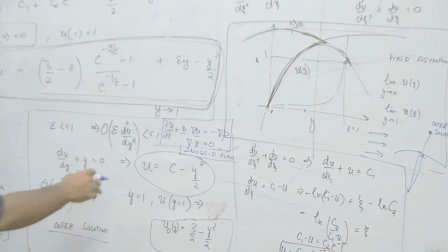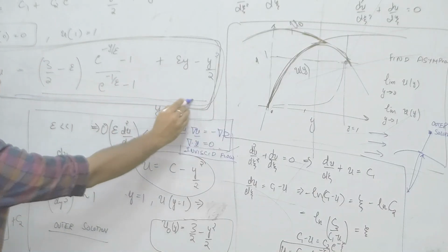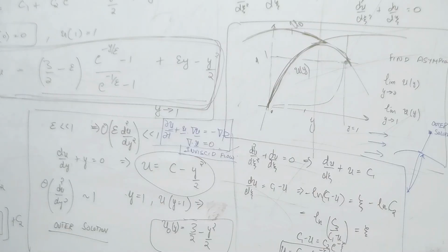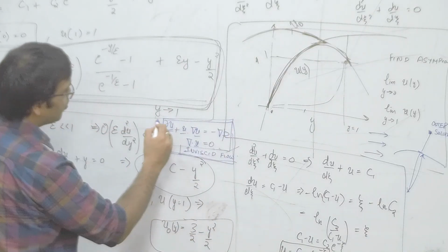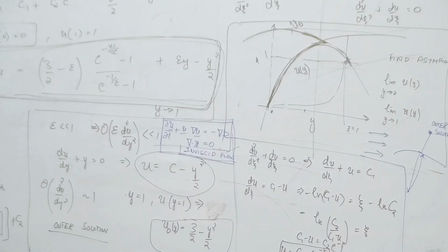And now, we don't know the analytical solution of this equation just like we did in this case, but we have some physical boundary conditions and physical reasoning which can help us out in determining which boundary conditions will take a hit when we specify inviscid flow. Some boundary conditions have to take a hit because we don't have second order equations anymore, we have first order equations. Which boundary conditions will not be applicable anymore?